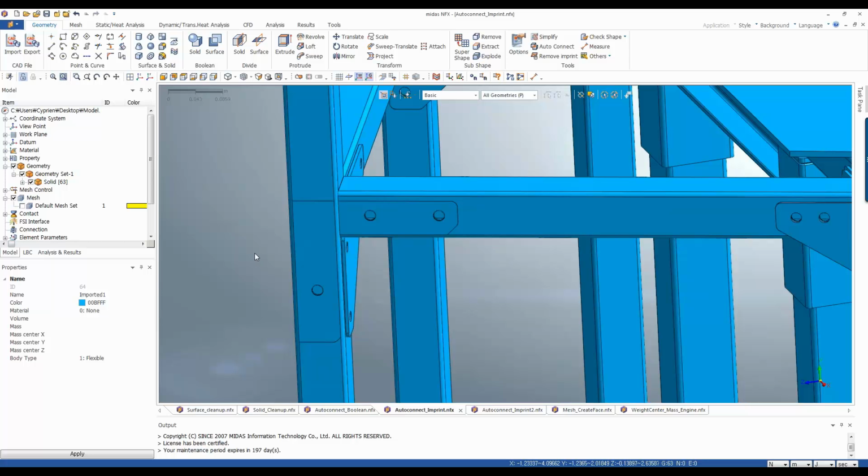Or for example, we can assure the contacting faces will be, let's say, much more compatible. So in terms of the contact, we don't have to select all of them of the model, and specifically the number of the contact elements will be less. So that's the second approach.